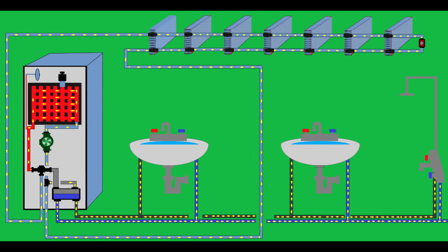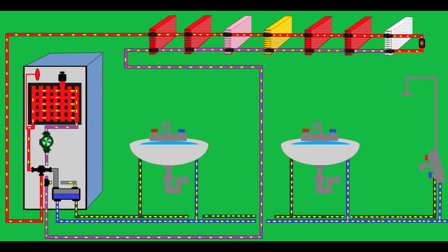You'll hear inside the boilers kind of knocks, and probably you'll have a little bit of steam, the pressure will be increased. And another side effect is that the pump will run crazy, and the pump will overheat itself because water will not circulate through the pump. So you'll have a high temperature inside the boiler, the pump will be red hot, but the boiler will stop on safety overheat. Make sure you will never override the overheat protection, otherwise very bad things will happen. I think this is for today.